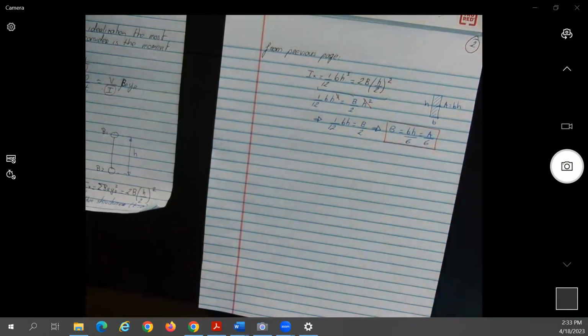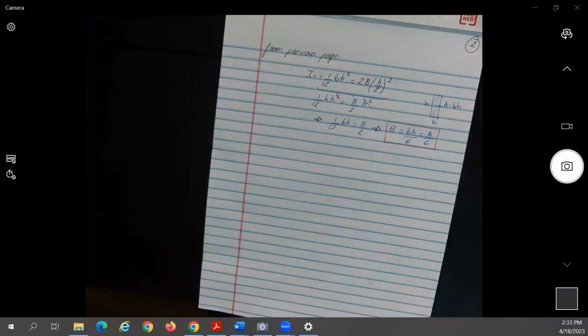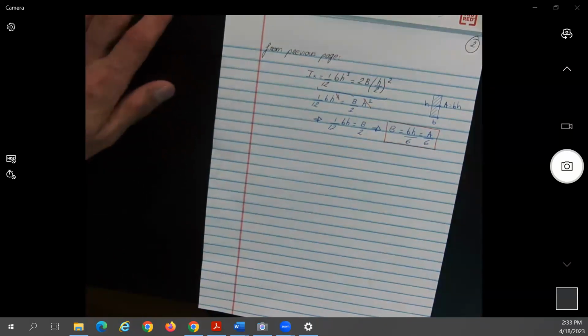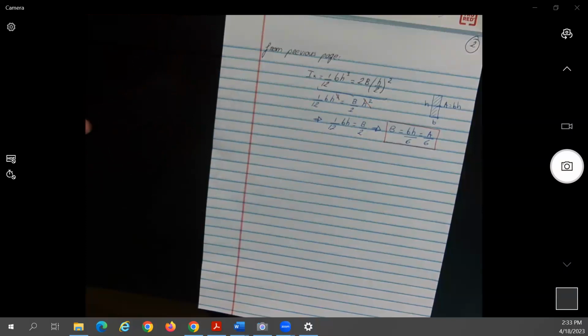Okay, and if you started working on the project, the Nastran project, basically it is the same idea. If you look at the calculations, what are you trying to model for the stresses? The moment of inertia of what would be just one panel, a simple panel, no? Okay, you have the simple panel. So that one has an I, no? Whatever, 1/12 b h cubed.